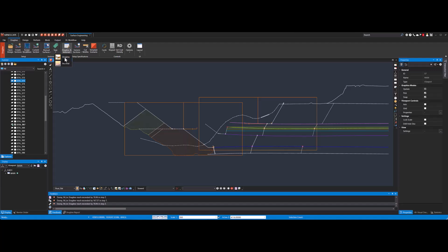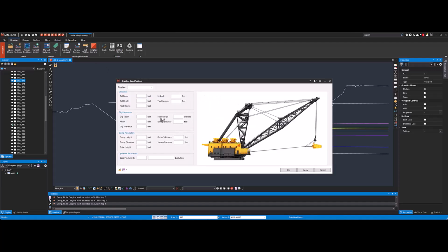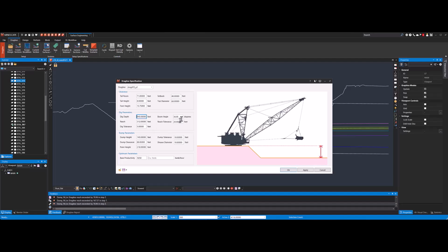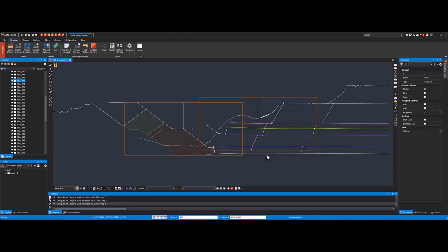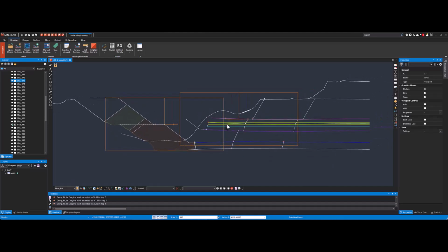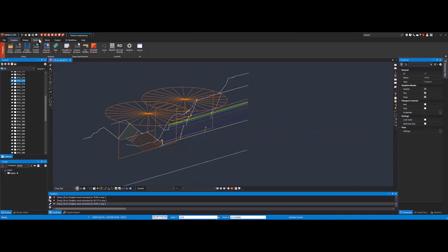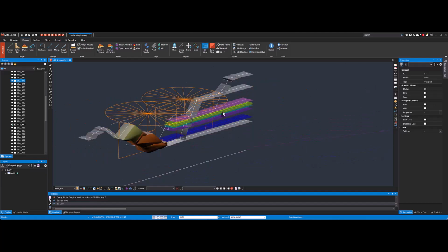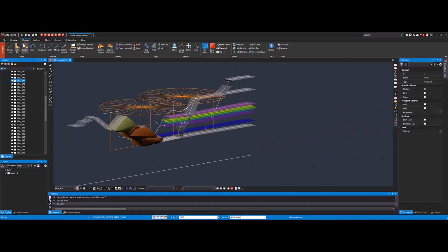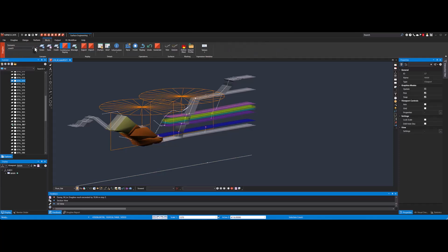Engineers can define and store customizable operating parameters for different dragline units and assign material characteristics like swell to specific stratigraphic units. Using a cross-sectional approach, the application automates movement processes, displays cut and spoil geometries, and ensures volume conservation. The replay functionality enables full spoiling simulations across multiple sections, creating 3D surfaces for multipass mining, optimizing rehandle strategies, and evaluating pit designs.